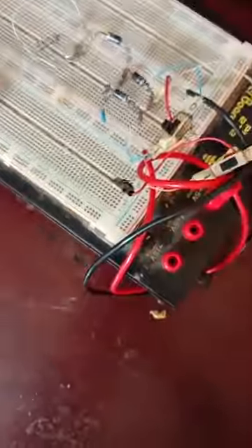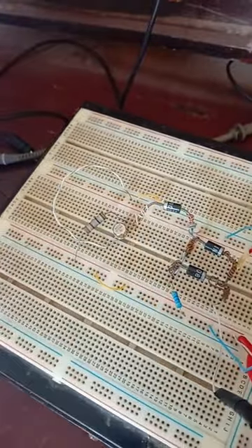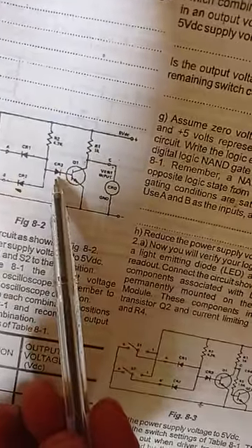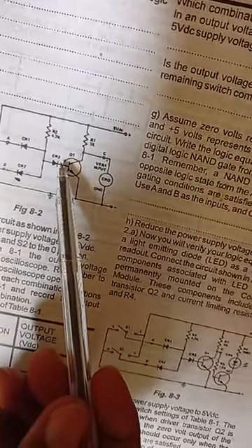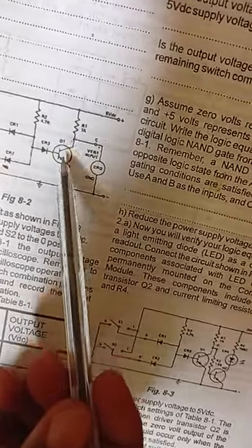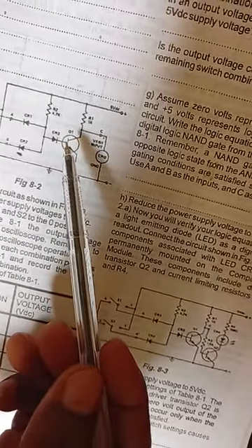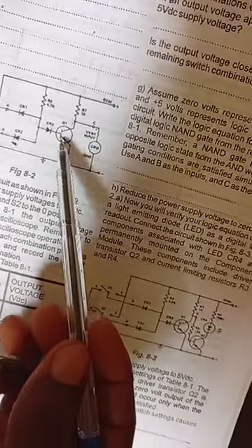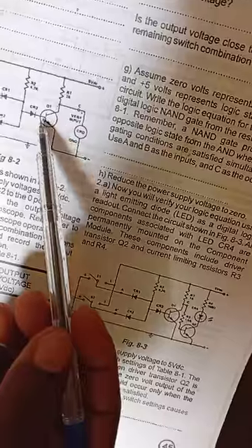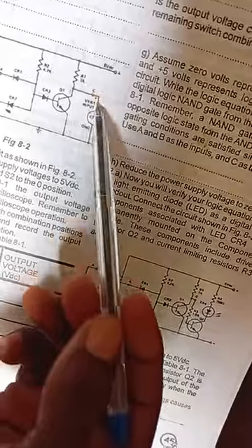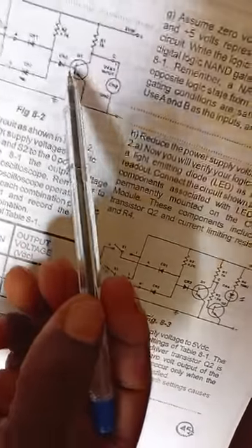This is the circuit. If you look at it very well, this is the transistor given to us. Then we have to use a diode at the back of this transistor, with the negative of the diode connected to the base. Emitter, base, collector. This is an NPN transistor, 2219, I think. Yes, that's an NPN transistor. So the emitter goes to the ground, the collector goes to our oscilloscope and a resistor, and then the base.